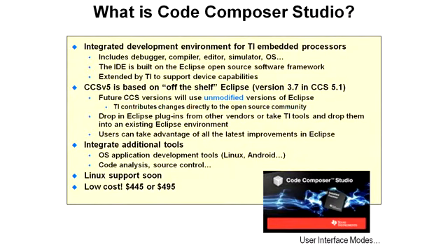Code Composer Studio is an integrated development environment for TI embedded processors. What do we mean by integrated? It means it includes the debugger, the compiler, the editor, the simulator, any support for an operating system that you might have, all of those things together in a single tool that you can use to program the device.